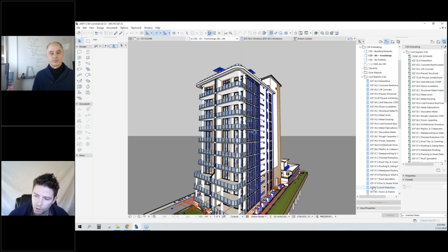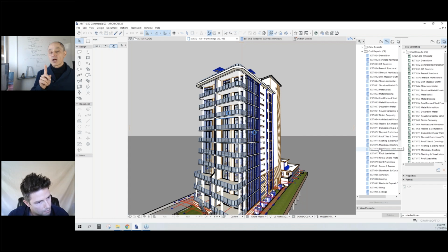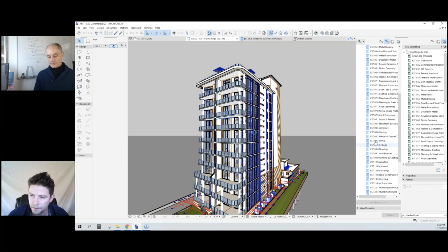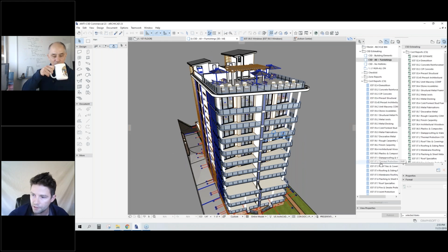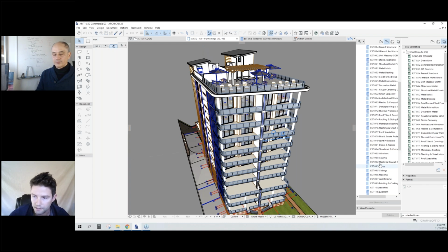What we've done here is load it up with the ContraBIM 5D estimating framework, so that we have all these different reports set up and going. Thank you to Gerald Hoffman, Canadian building designer, for sharing this project with us. Yeah, absolutely, a really cool project. Within this, you can see I've broken up all these different reports. I generally like doing this by CSI MasterFormat here in the US, which is a really nice, clean way of organizing cost codes and allows us to correlate between specifications and the trades of construction.